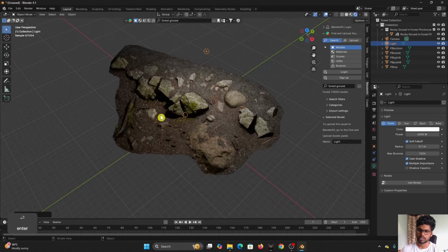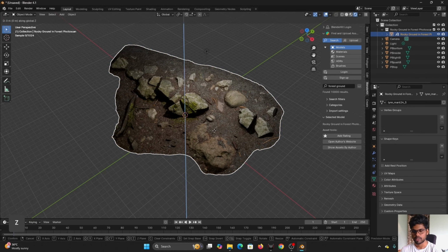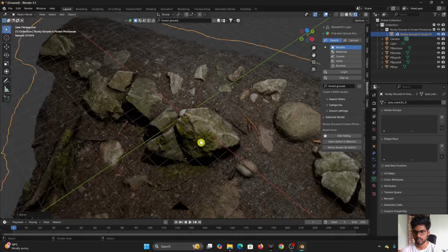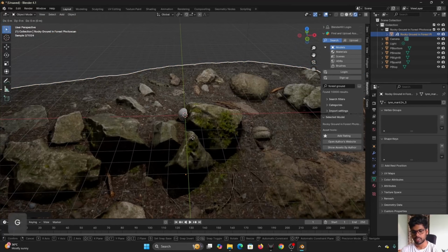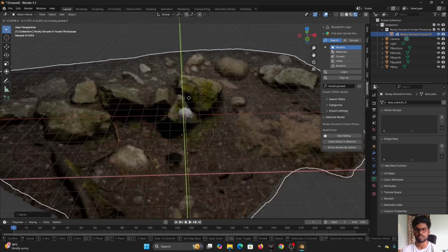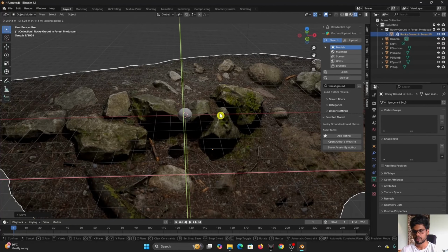And now I'm going to adjust the location of the floor object so that we have the Pokeball in our desired position. I'm going to do that with G and let's say Z, so that our Pokeball is on top, that's somewhere there. And now I'm going to hit G and Shift Z. So when you hit G and Z, you're telling the program that you want to move in the Z axis. And when you hit G and Shift plus Z, X or Y, you're telling the program that you want to move it in both the axes other than the axis that you've selected. So Shift Z means I get to move this object in both X and Y directions. So we'll place it somewhere here.